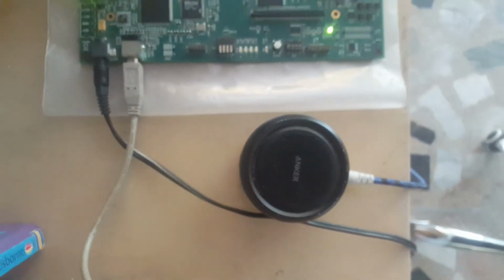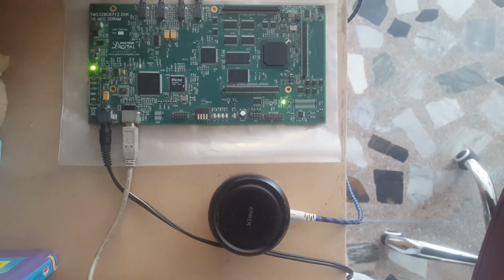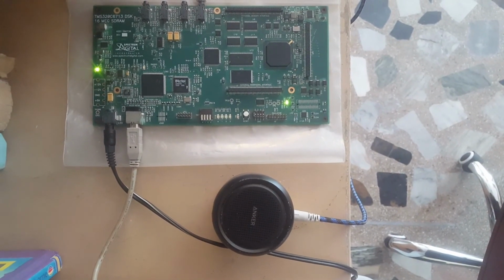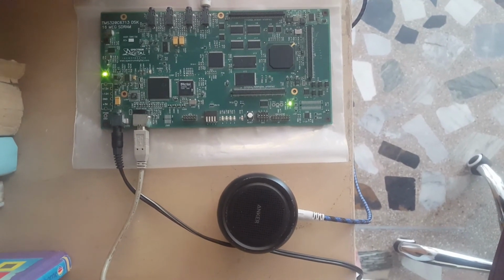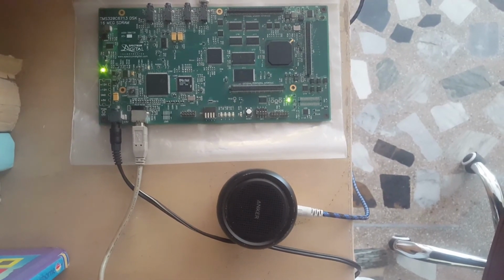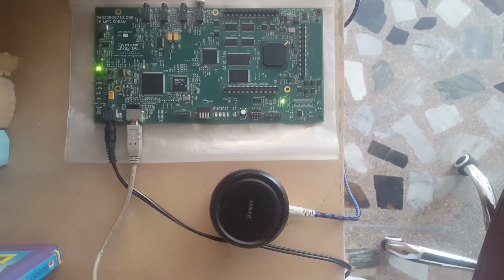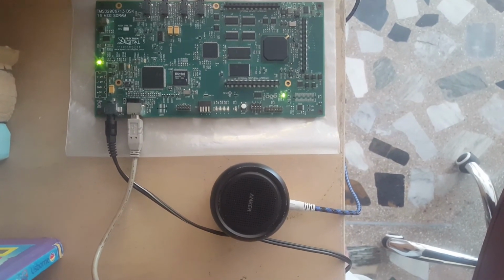Now this sound corresponds to the sinusoidal signal that was generated in our code. Changing the frequency of our code will simply change how this sound is produced. Changing the gain of the system will only change the intensity of the sound being heard from the speaker. So this completes our task number 1, where we have successfully generated a sine tone, and we have heard that sine tone on the speaker using the AIC23 codec.